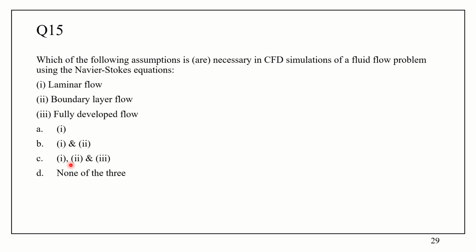That is, these three assumptions are not required for solving the Navier-Stokes equations. Laminar flow or turbulent flow, it works. Boundary layer flow or fully developed flow, these approximations simplify the equations, but it doesn't mean that these assumptions are necessary for CFD simulations of a fluid flow problem with the Navier-Stokes equations. So none of the three is the right answer, and it is option D.